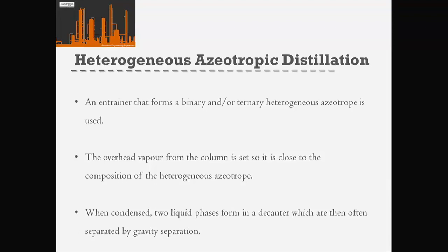Liquid-liquid separation, the equilibrium separation of two liquids, is a different type of separation. So potentially, that gives us the advantage that we can actually cross distillation boundaries because we've got that different type of separation in our system. And also, quite often the two liquid phases we get, if we just let them settle in a decanter, will form those two liquid phases just by gravity. So actually, it could be a very cheap separation as well.